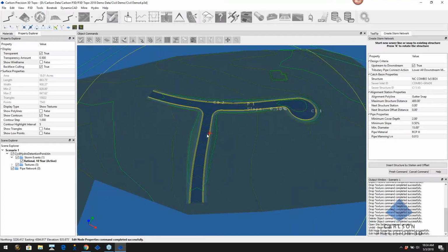Again, come down through here. Boom, there's a low point. Straight across the street's another one. Boom, pick it. You see, now what's happening, if you look at this pipe slope, it's at minus 2% because this pipe is cover dictated down here at the low point with me.